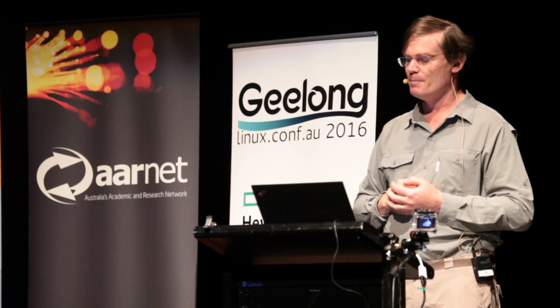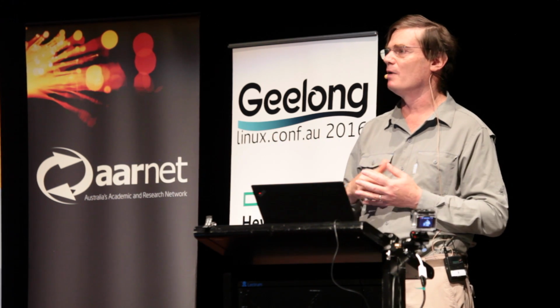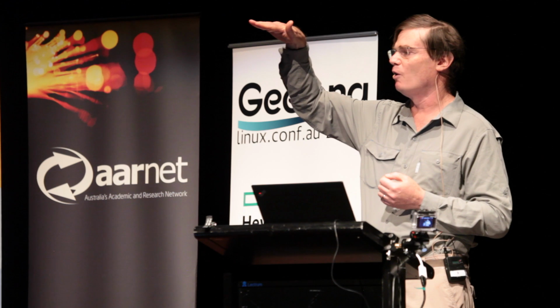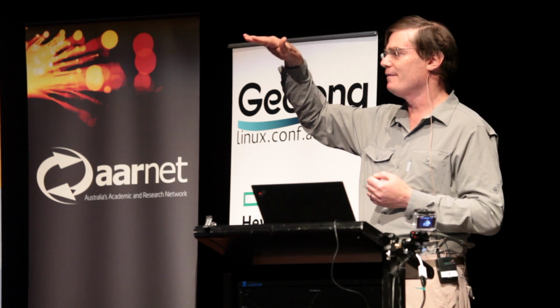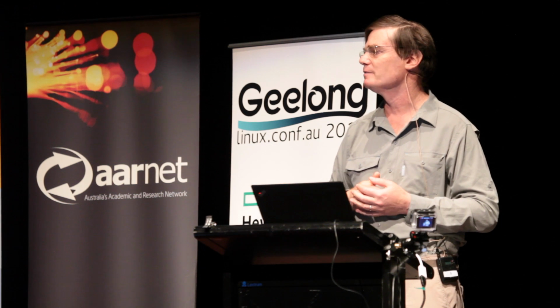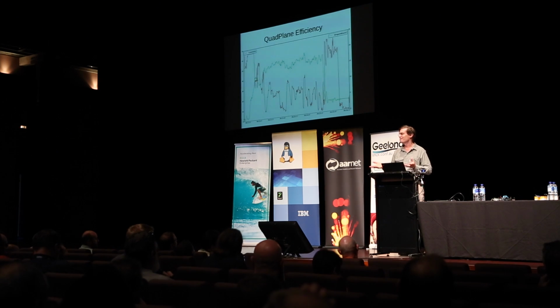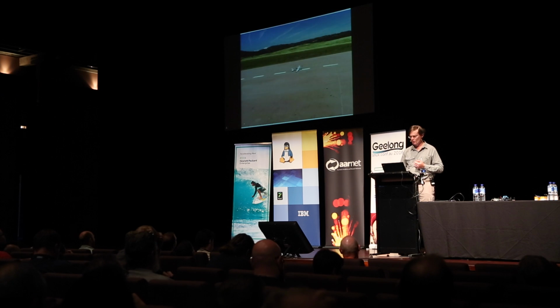So the batteries in our quad plane, for our larger quad plane, might give you a couple of minutes of vertical flight. And that's with 4 or 5 kilos of batteries in a 19-kilogram plane. The petrol, which might be only a litre and a half, will give you maybe an hour at 100 kilometres an hour, right? So you get this massive efficiency in forward flight. So let's have a look at what that looks like.